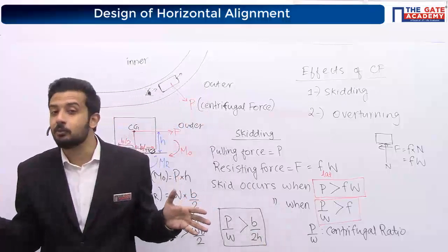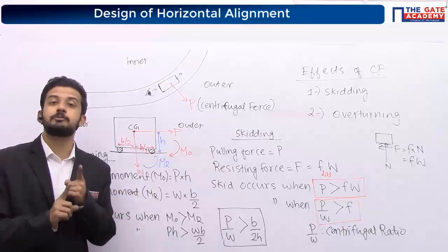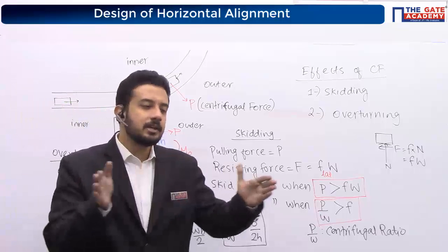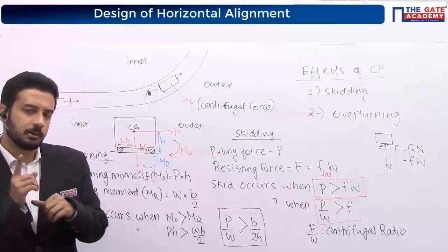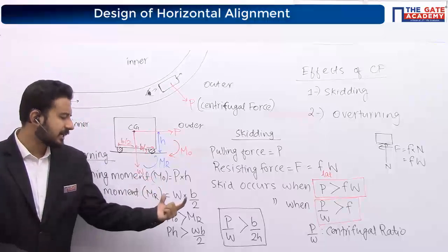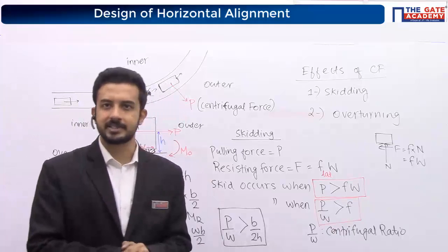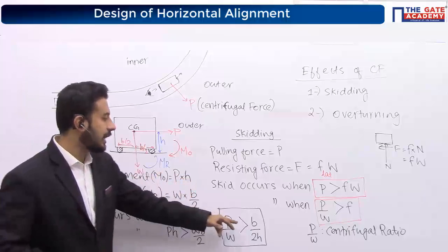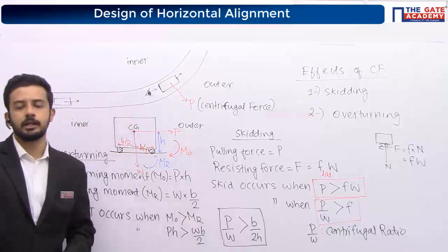Okay. Width of the vehicle. Maximum width of the vehicle is 2.44 meter as per IRC. That's why we were giving some 2.5 meter width for the shoulders. Remembering the previous class, maximum I can give 2.44 only. We already discussed that. So we cannot increase the width, the value of B, to reduce the overturning.